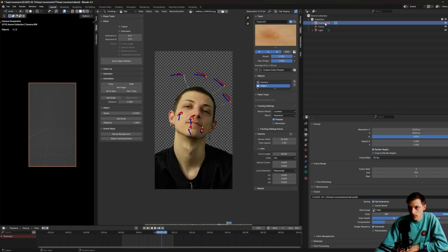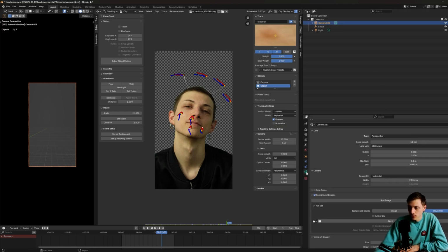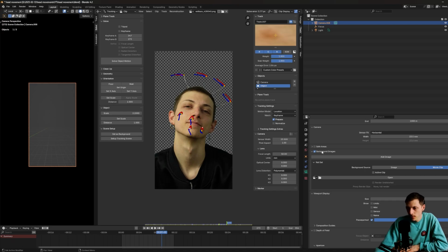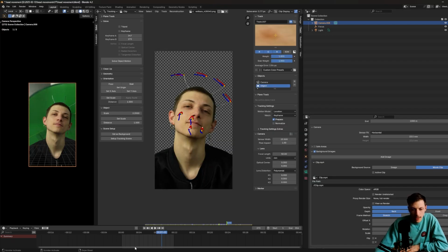And then we have to add the video to the camera. So we click on the camera and then we go to this tab, and here under background image, add image, and in this case movie clip, open. And that's it. Now, if we play here in the timeline, we play the video through the camera.